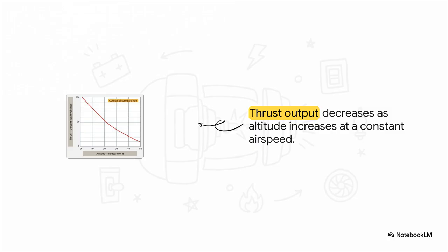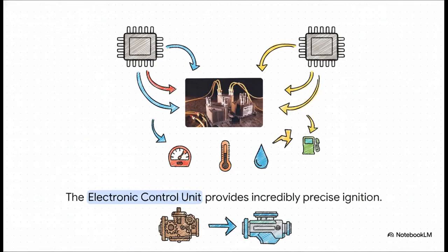As future maintenance technicians, you absolutely need to understand these performance metrics. Part of your job is ensuring that the engine is capable of sustaining that continuous combustion safely, even when atmospheric pressure drops. We're also going to briefly look at the modern hardware you'll be handling out there, like the Electronic Control Unit, or ECU. Today, digital computers have completely transformed fuel and ignition metering. Each ECU contains multiple microprocessors that are constantly interpreting signals like pressure and temperature, providing incredibly precise, redundant control over fuel injection and ignition. It makes the whole system highly efficient, and honestly, it's a long, long way from tuning old mechanical carburetors.